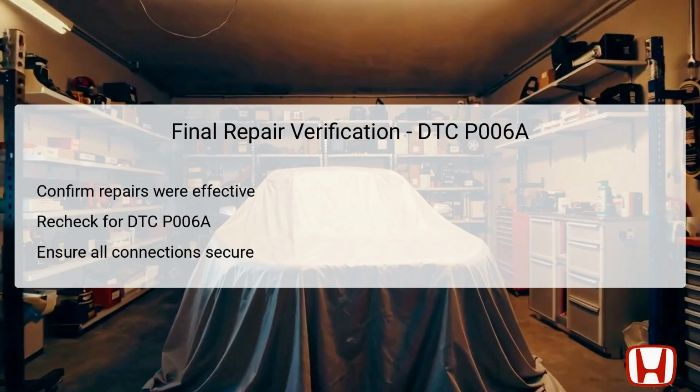The final step in this troubleshooting guide is to conduct a repair verification process. After any repairs have been completed, it's essential to confirm that the system operates correctly and to check if the DTC P006A has cleared. Utilize the HDS once again to ensure no fault codes remain in the system.